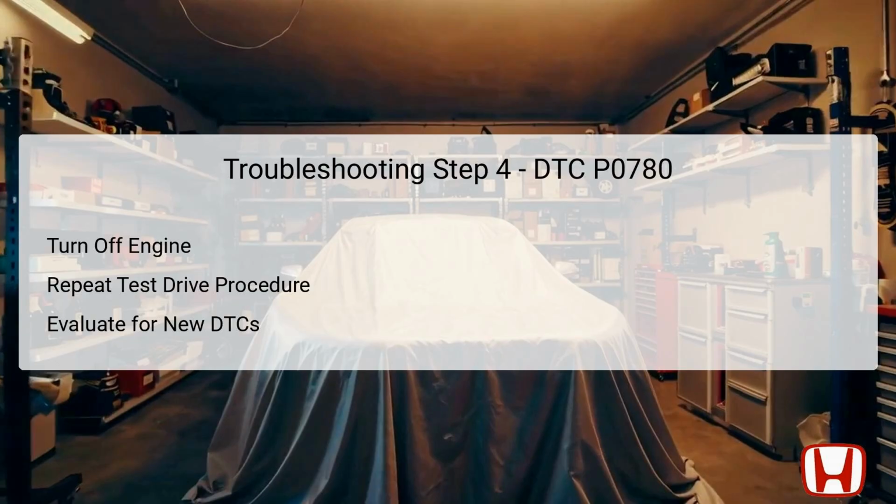correctly. Following this second test drive, it is essential to check the system again with the HDS for any new pending or confirmed DTCs that may have emerged. Identifying additional codes can provide further insight into the health of the transmission and guide next steps.